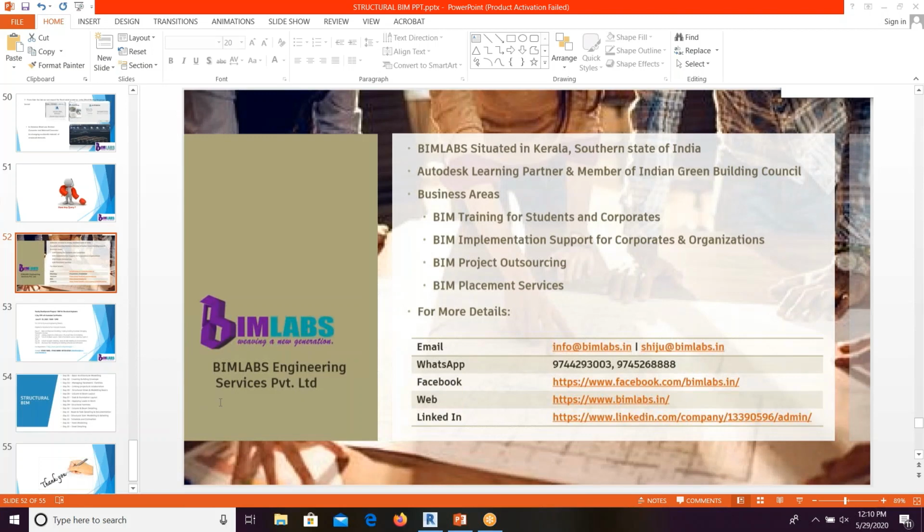Yeah, Yadu, we have a platform called Navisworks. In that, the Revit architectural file, Revit structural file, as well as Revit MEP file can be added, so that if you have any clashes, that means we may have a clash between the column, beam and some duct going on and all, those clashes can be detected there and easily rectified. After we run the clash detection in Navisworks, a zero error model will be out for the construction.